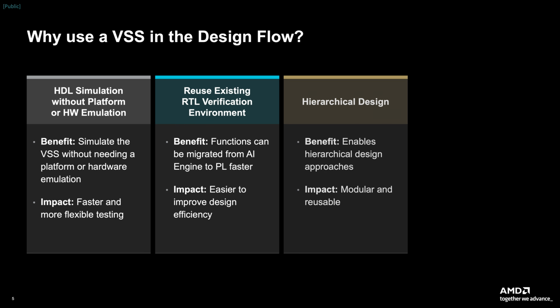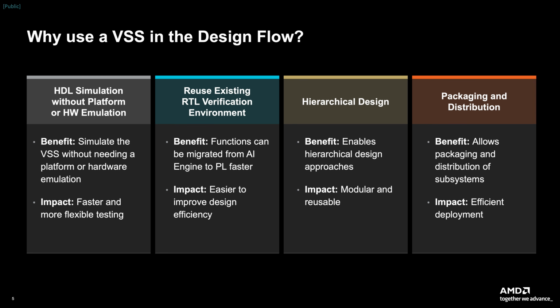The VSS flow simplifies development, testing, and delivery of heterogeneous designs. A top-level HDL test bench can be used for simulation without a platform or SIPs. This allows for more flexible development and testing of interconnected graphs and kernels.